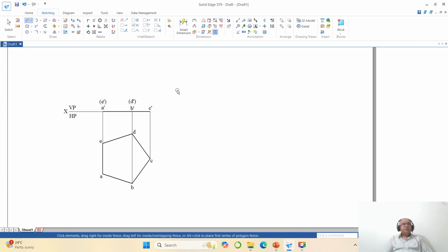Okay, fine. Now you go to move, select this entire line, click the point to rotate from, so you take this point. So now it is moving in both X and Y. I don't want to move in Y direction, so take the tab and move to Y coordinate, make it 0. So here you put the copy on, so place it wherever you want, then click on the first button of the mouse.